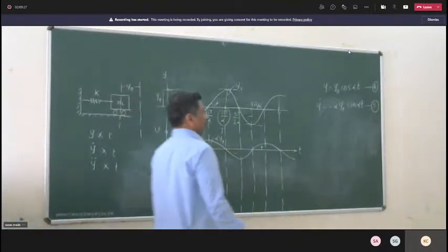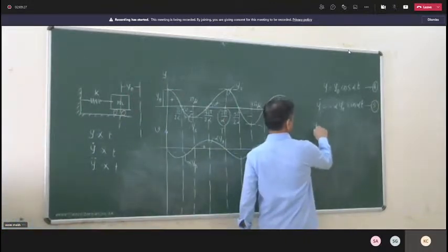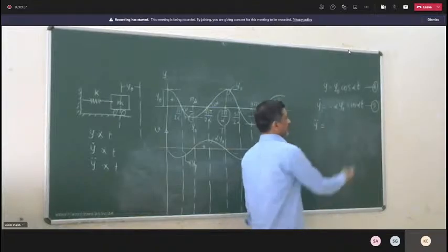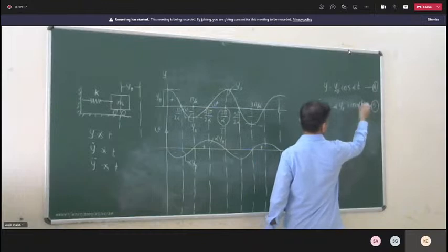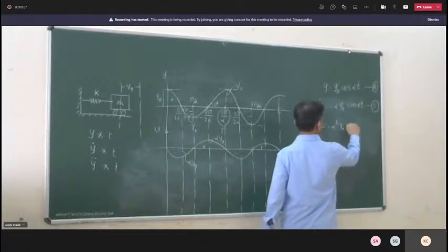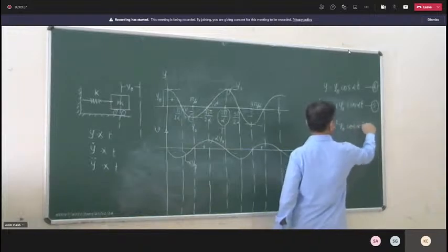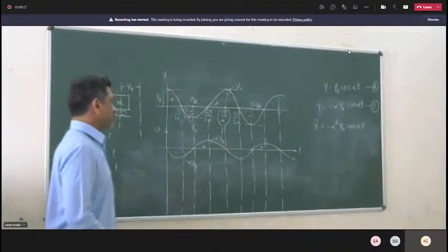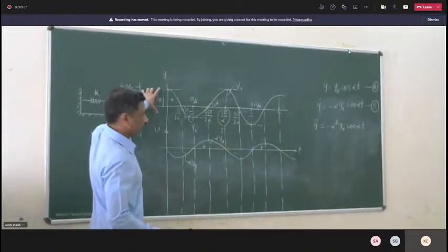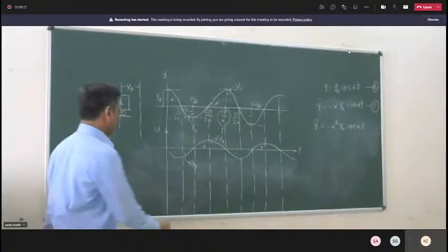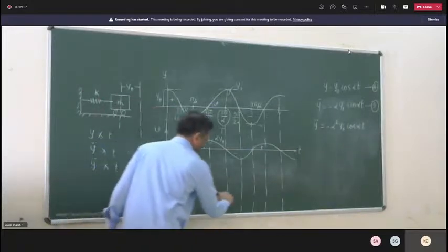Well, if I want to find the equation of acceleration, take the derivative of equation 5 further. So derivative of sin alpha t is alpha cos alpha t. So minus alpha square y0 cos alpha t. So again, acceleration versus time graph is a cosine curve. The ordinate at 0 and it has to be plotted on the negative side.